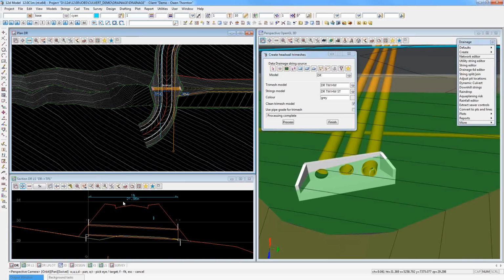You know, you can imagine that throughout a job you could quite easily have a mix of different flow directions if that was the convention you wanted, of always keeping the road side on the left on your long sections of your culverts. So yes, we do support that. The only caveats of having mixed flow directions is you can't join two drainage strings together that have different flow directions set. Other than that, it's perfectly fine.